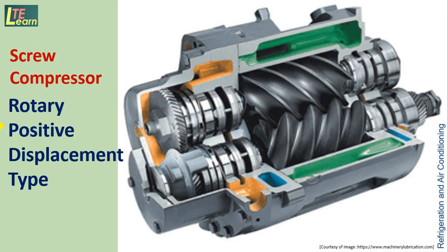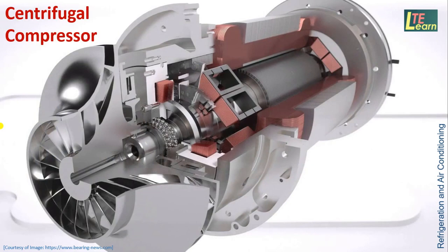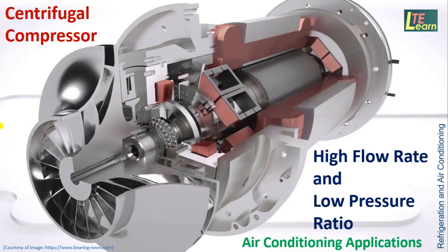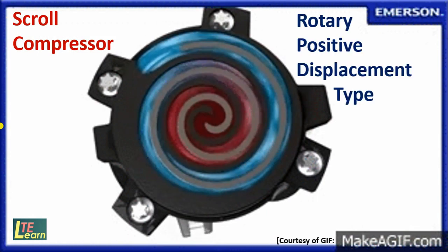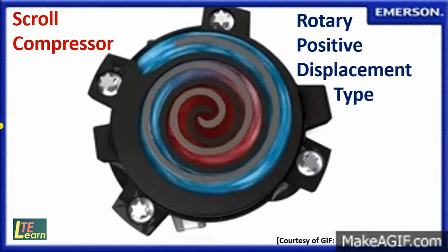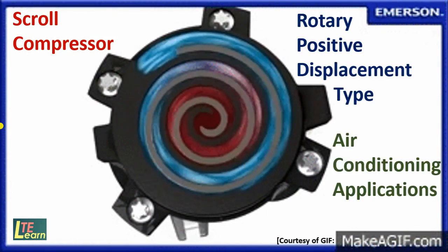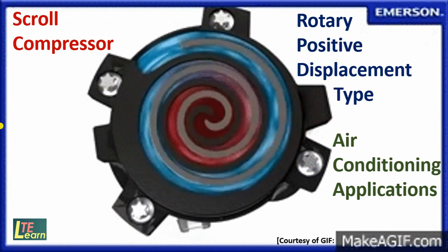Screw compressor is a rotary type displacement type compressor which is used in process industries. Centrifugal compressor is used in air conditioning applications where high flow rate and low pressure ratio is required. Scroll compressor is a rotary positive displacement type compressor which is used in air conditioning applications.